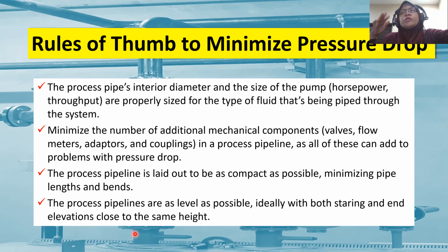But of course, we need to have a little bit of slope to allow full drainage, so that when you want to drain the liquid from the pipe, it is easy. That is under hygienic consideration.